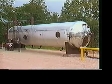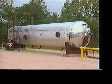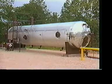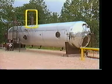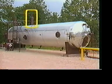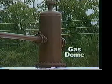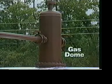Now, this unit is designed internally to equalize gas pressure between sections. However, some units have an external gas equalizer pipe which allows gas pressure to be equalized and collected. Gas leaves the treater through a gas dome before it enters the gas outlet line. The dome is designed to remove any liquid particles entrained in the gas stream.